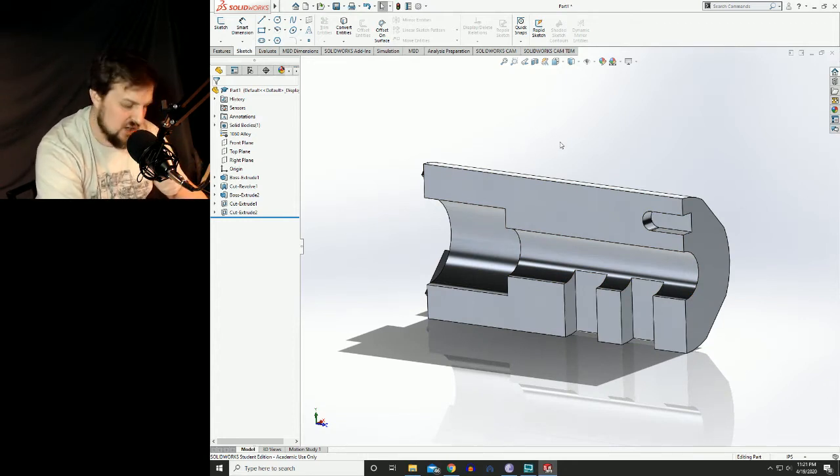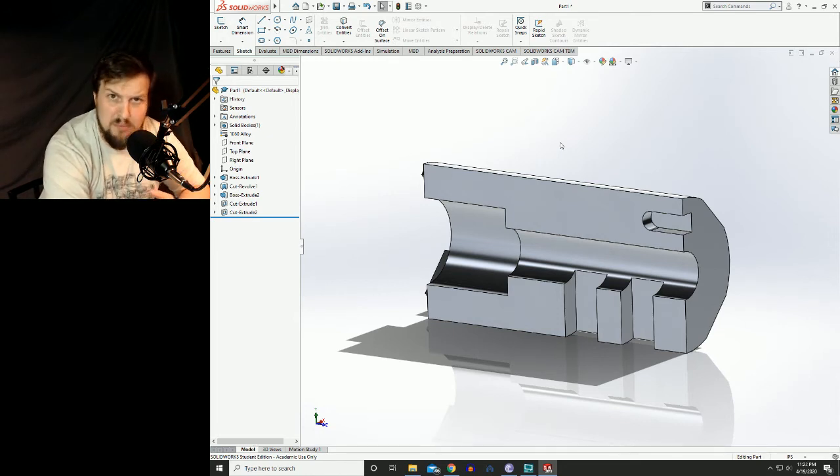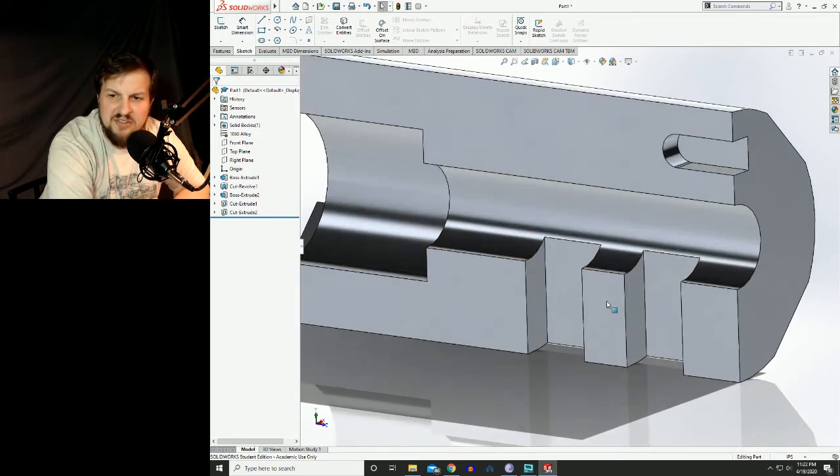Okay, so the very last thing that we need to do now is we need to find the mass on this thing. So the book's asking for the mass, but I'm going to show you how to find one better too. The reason that it's looking for the mass on this is because the way that the CSWA exam judges how you did is based on the mass. When you go out to 3 decimals on a pound mass system, generally speaking, that's close enough that they're going to be able to tell if you're off.